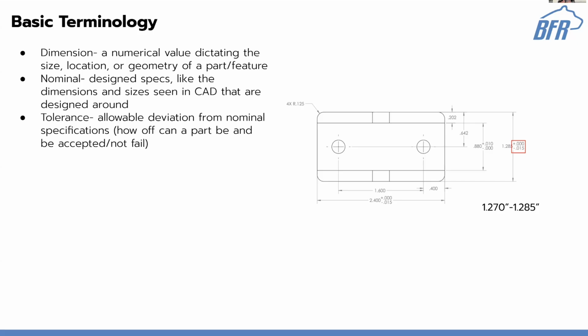A good drawing will very clearly show you the limits. With some of them, you actually have more wiggle room beyond the tolerances of the drawing. Someone might not have done all the work to set a certain tolerance correctly, so if it's out, they might say, "Oh, it's still fine." But yeah, tolerance is how much error you're willing to accept, right? And if you're reading this in the drawing, you'll see all these plus and minuses. This is one way of indicating tolerances besides those standard ones at the bottom.